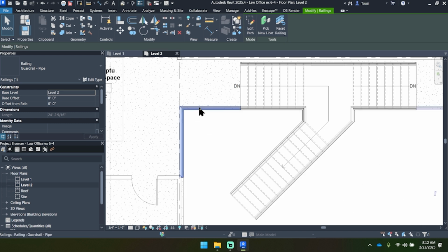The next step will be adjusting the handrail to have a profile on it so that we can have the flooring side profile match the stringer that are on the stairs. If you look on page 8-47, at the top on figure 8-3.12, you'll see that there is a thick profile on the sides of the stairs acting as the stringer, but then when it reaches the floor, there's a very thin floor, and those two profiles aren't matching each other. We want to carry that thick profile on the sides of the stairs all the way around the floor system.